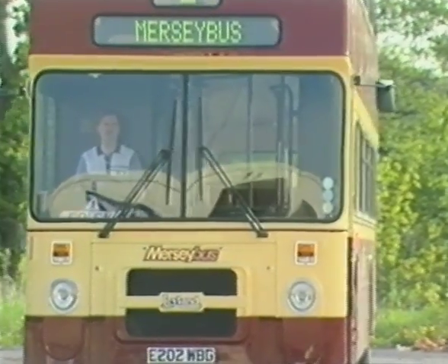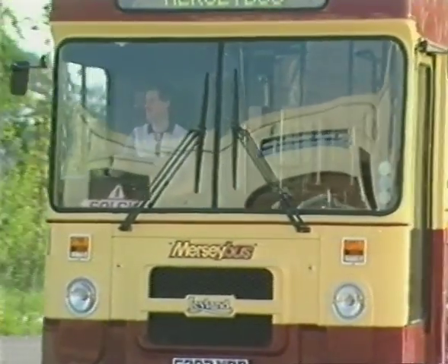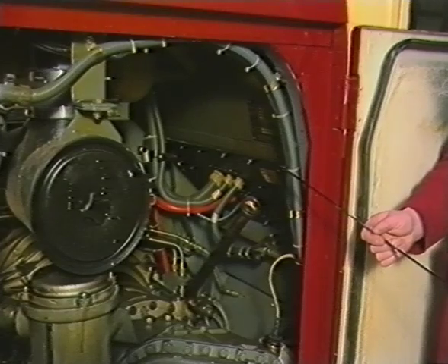To complete the refill procedure, bring the gearbox to the normal working temperature of approximately 80 degrees centigrade. With the engine at idle, the oil level, if correct, should be between these two marks. This final procedure is known as a hot check and is the only accurate method to establish the precise oil level and should therefore be used at all times.